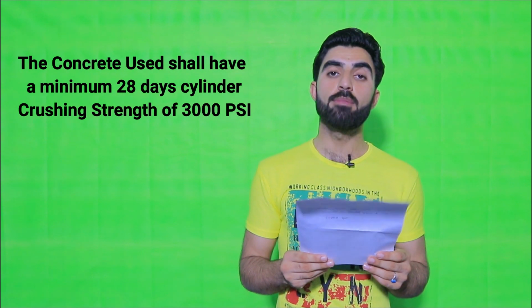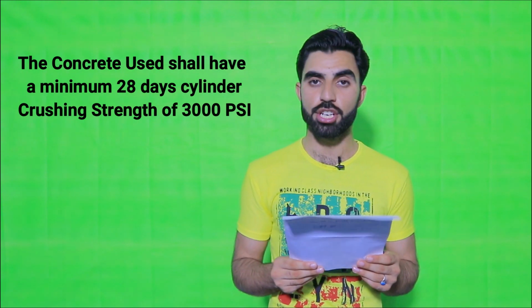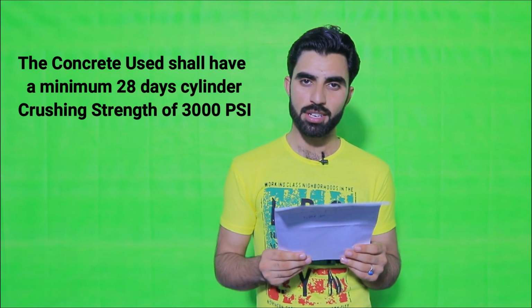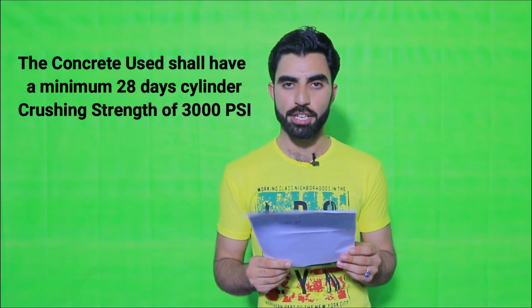Okay guys, the fourth point is that the concrete used shall have a minimum 28 days cylinder crushing strength of 3000 psi, pounds per square inch. As you know, to get 3000 psi, the concrete mix should be M20 grade. So when you want to get the full strength of M20 grade concrete, the concrete used shall have a minimum 28 days cylinder crushing strength of 3000 psi. This is another useful point, and you should write it in the RCC drawing.